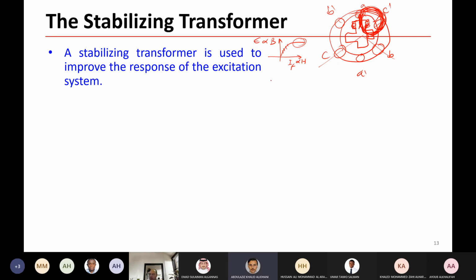So this is the way. Okay Doctor, what about constant resistance? This is like a non-linear characteristic, or loaded, this is the loaded machine. You have the load as constant resistance, and you increase the field current. And we have here three curves, like the air gap.